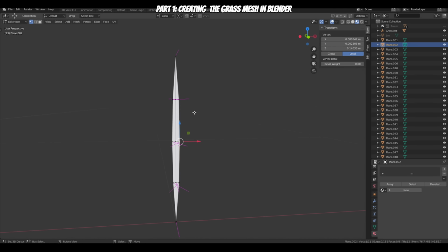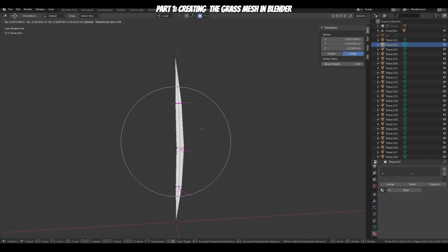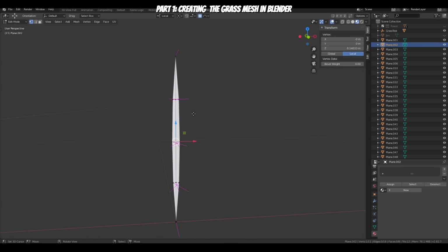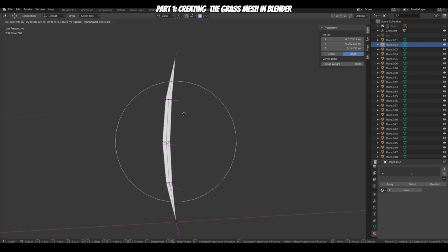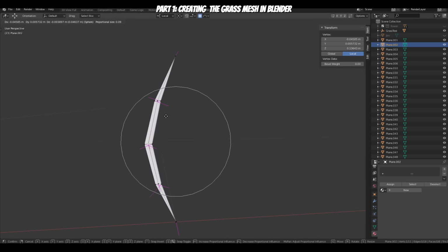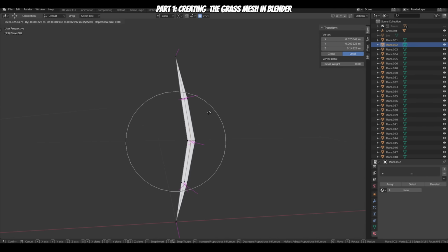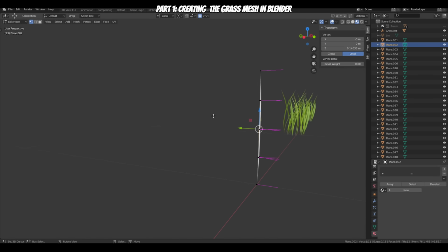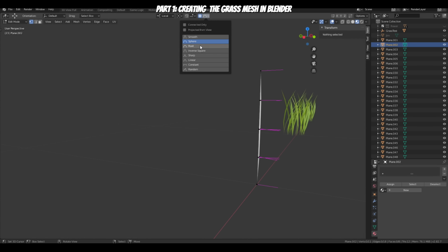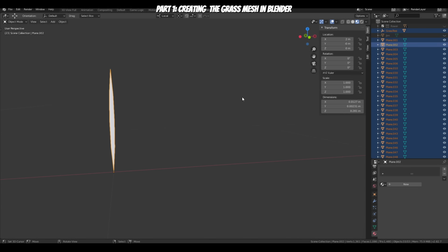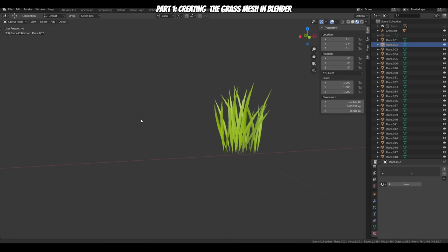which, if you press O, first you press O and then you press G or any sort of move. And then you use your mouse wheel to adjust how big the area of the proportional edit is. And it works on every axis too. You can also edit how you want it to be, like smooth or sphere-like or sharp, linear. Anyway, you can edit the sort of mask, I guess. The falloff type, yeah. All right, so here's your grass strand. Just stamp it around.